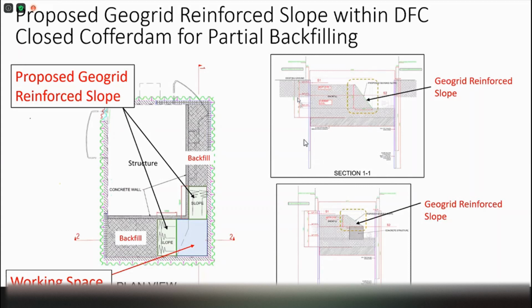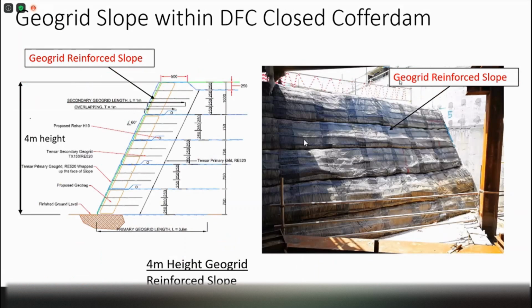So in order to sustain the angle of the slope, we eventually designed a geogrid reinforced slope within the deep excavation ERSS. So it's a very interesting application of geogrid. This is eventually how it looked. We provided the geogrid, which is again RE. We use RE series for the reinforcement, and then we do not actually provide any facing. You can see the soil actually exposing. It's exposed, but in this case, we are not so particular about erosion. Because it's within the excavation site, so we just need to maintain the stability of the slope. So this is a very special application.